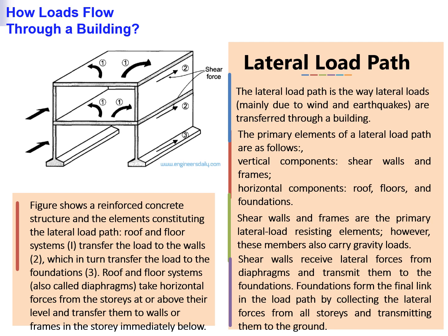Roof and floor systems: 1. Transfer the load to the walls, 2. which in turn transfer the load to the foundations. 3. Roof and floor systems, also called diaphragms, take horizontal forces from the stories at or above their level and transfer them to walls or frames in the story immediately below.